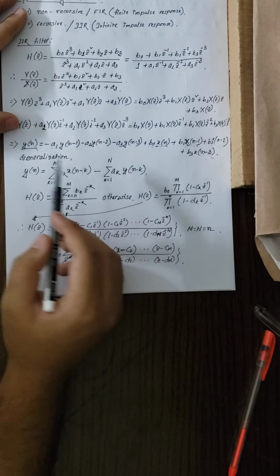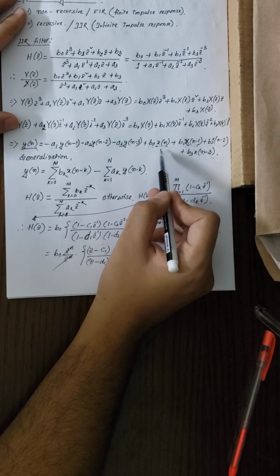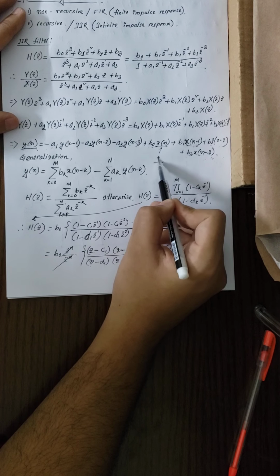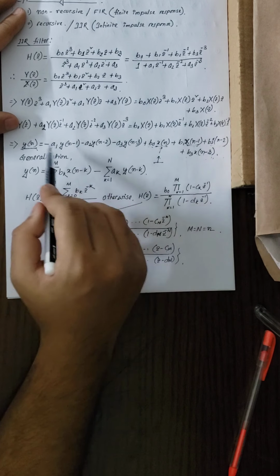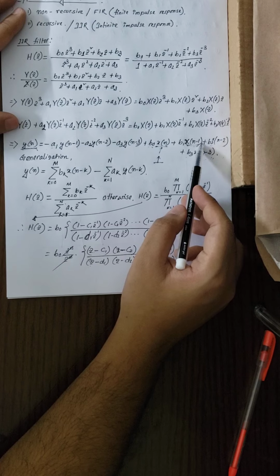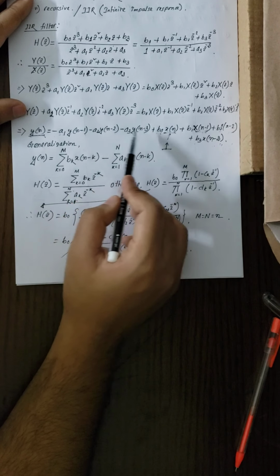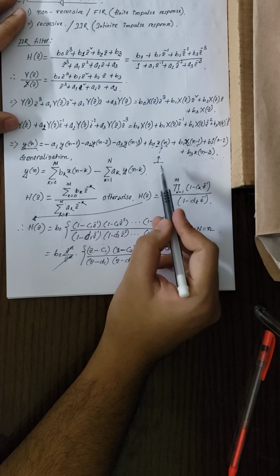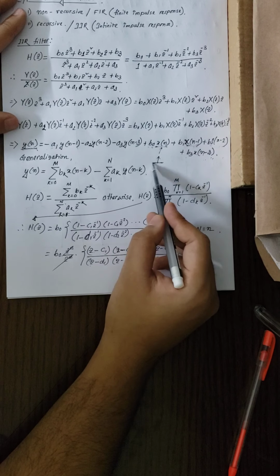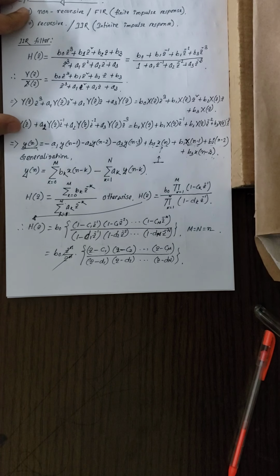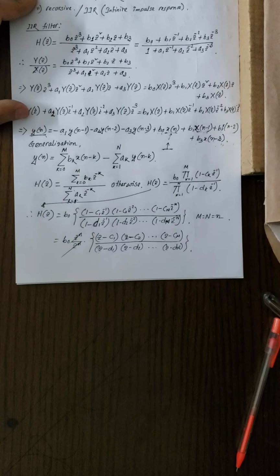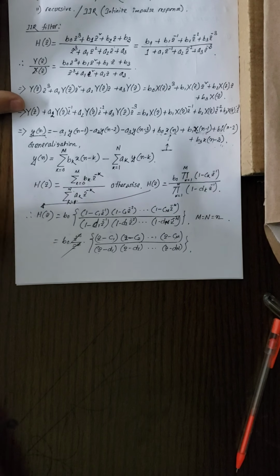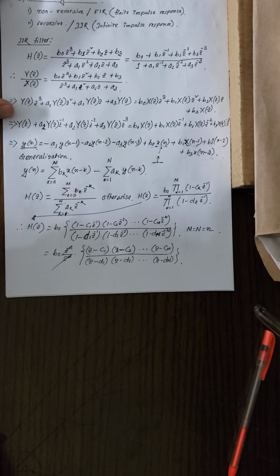The first is, if we give an input to the system, a single impulse function, due to the nature of the IIR filter, this past value will always be present, and essentially this impulse signal will repeat an infinite number of times in the output, hence the name infinite impulse response.